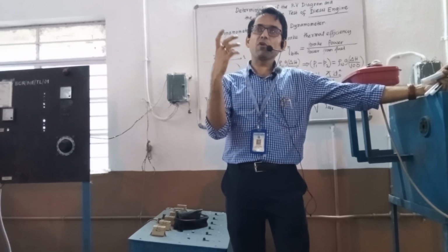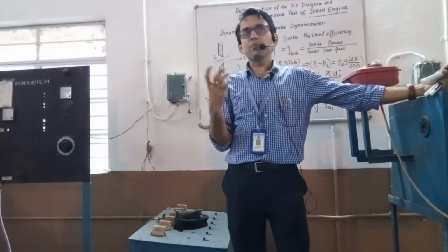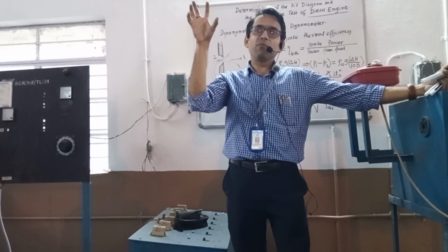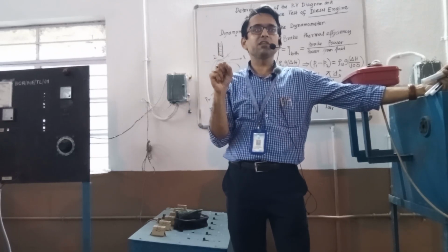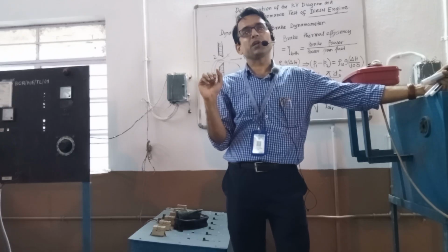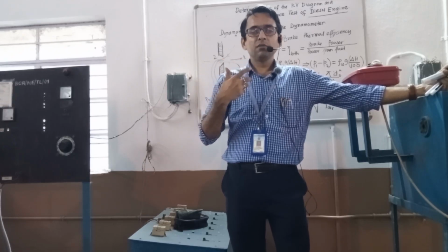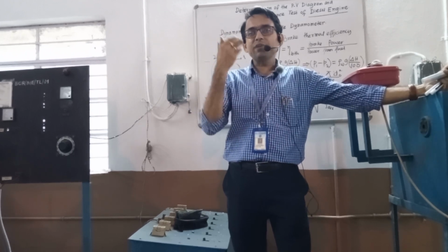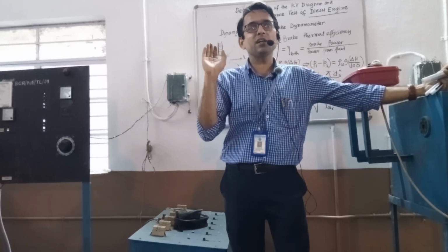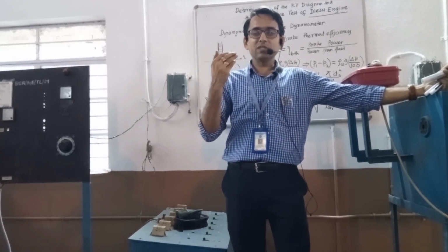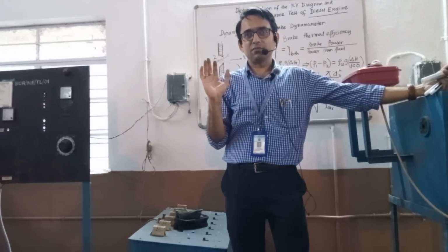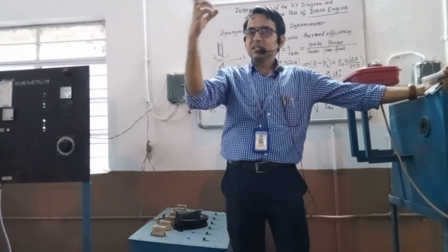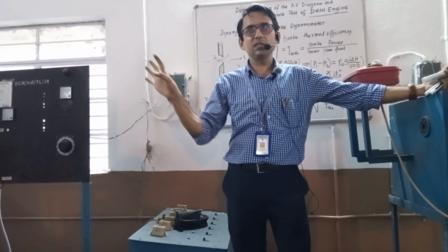But there is a concept of volumetric efficiency, which you have studied in air compressors also. It is the actual volume flow rate through the engine divided by the maximum possible volume flow rate. For example, if my lung capacity is 1 liter but I inhale only 700 milliliters of air, my capacity utilization is 700 divided by 1000, that means 70%. So my inhaling capacity is 70%. This is called volumetric efficiency in the case of an engine.